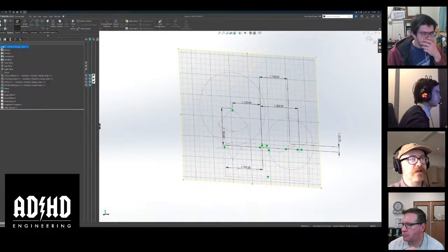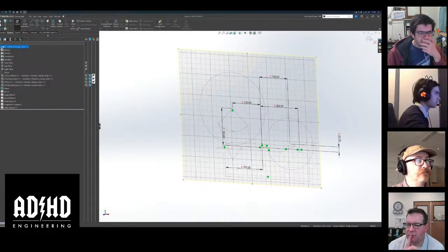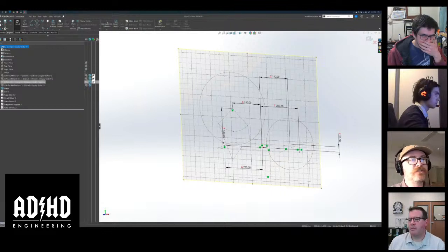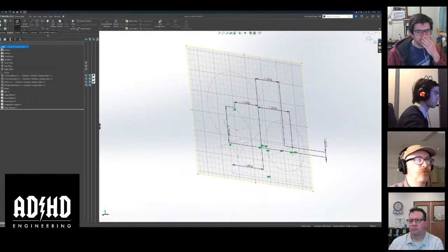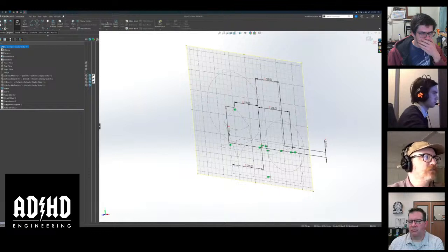Yeah. So one thing to keep in mind, and I don't want to confuse anybody, but you can also create planes in this 3D sketch that live only in this 3D sketch. They won't appear in the feature tree. They're not available for anyone else to use in any parts or components later on. They're just used specifically to create and orient blocks. So that's something you can use if you want to. And there are cases where you will actually want to put one of these blocks on a plane that isn't the origin planes. And I actually considered doing that. I probably could do that here if you want me to show you.